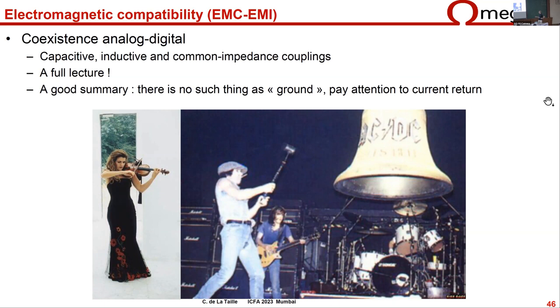This is something, one important thing to see the amount of difficulty, is trying to go back again to the fundamentals and try to see what is the voltage that you have on the input of your preamplifiers. So the voltage is the charge that you want to get divided by, again, your sensor capacitance, the capacitance at the input of your amplifier. In a typical pixel, you get femtocoulombs, but the sensor capacitance is a few tens of femtofarads. And so you typically get 10 millivolts, something like that.